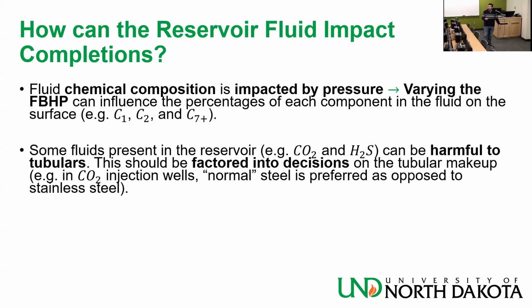It weakens the tubular significantly. So you don't want your wellbore architecture to be anchoring on something that will get corroded, because casing, you cannot really take the casing out of the well and change it, run new casing and cement it in place. It's not easy to do.